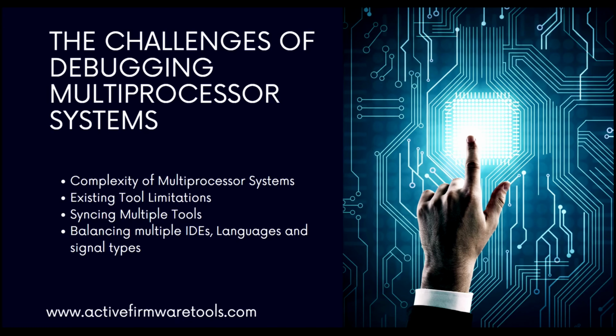Anybody who writes firmware knows what it takes to debug a single processor. We usually use an IDE, an integrated development environment. We burn or program our firmware into the device. We then use a debugger, which typically single steps or breakpoints or watches variables in that processor, and we can debug the program on that one processor.